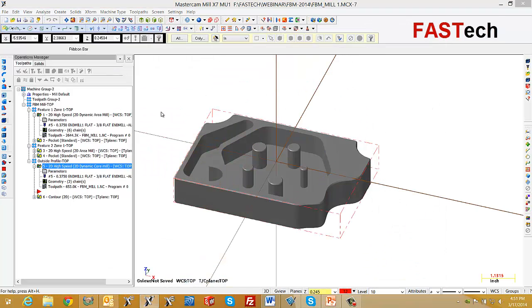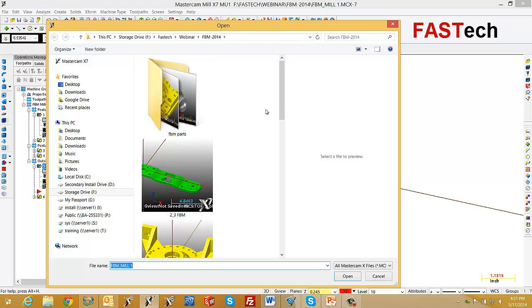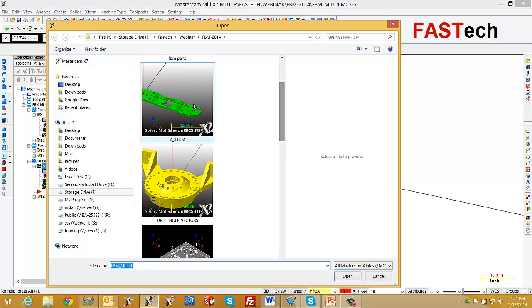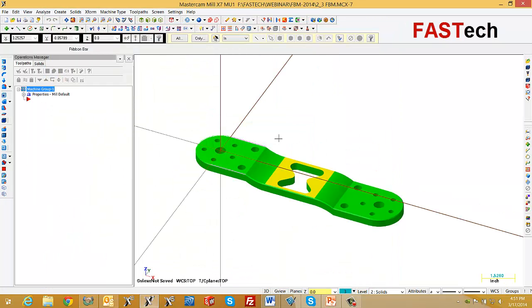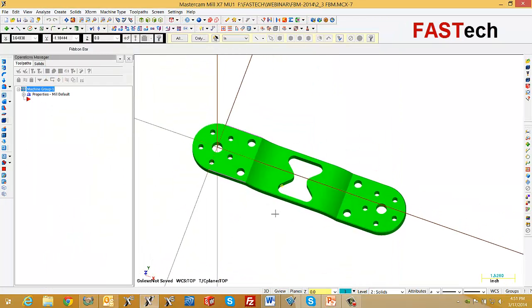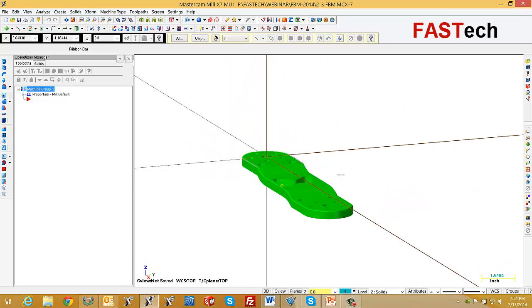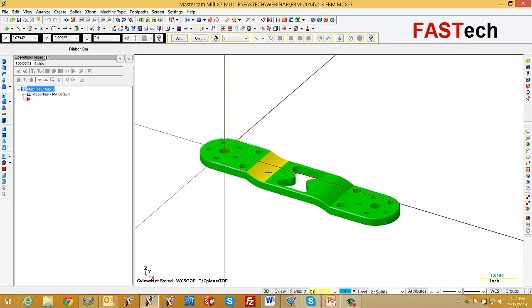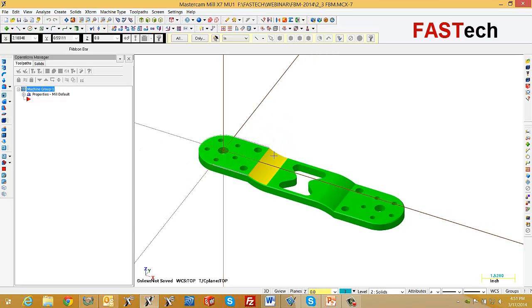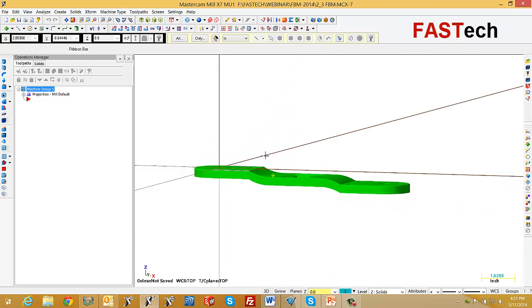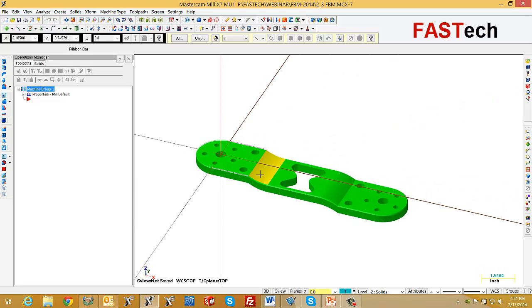There again, file open. And sometimes someone wants to combine a couple things together. Well, in this case, we'll do a feature-based mill. In this case, we've got a 2.5D. I always use 2D before I do 3D. And we see a little bit of 3D in here if we choose to. In other words, I really don't want to come in here with a big cutter and kind of cut that down. So watch how we attack this with the things that we learned today.